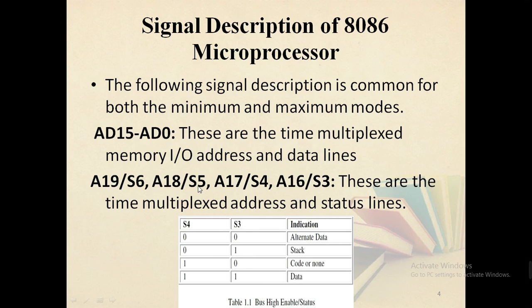And S5 represents the status of the interrupt enable flag bit. And S6 is always low. So the address bits are separated from status bits using latches controlled by the ALE signal.